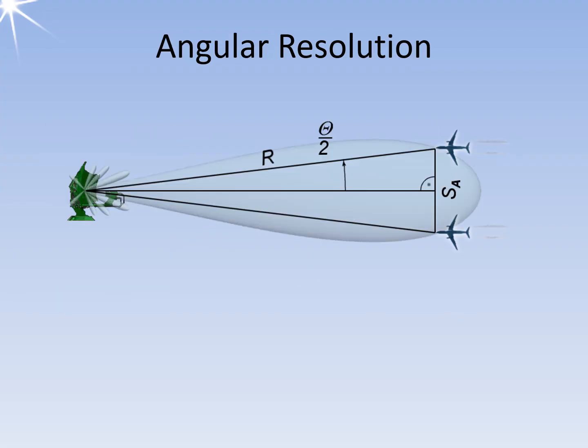Radar angular resolution is the minimum distance between two equally large targets at the same range which radar can distinguish and separate from each other. The angular resolution is a function of antenna parameters. It can be given directly as an angle or as a lateral distance between aircraft measured as a function of distance. The angular resolution characteristics of radar are determined by the antenna's half-power beamwidth, which is defined by the -3 decibel points. The half-power points of the antenna radiation pattern are normally specified as the limits of the antenna beamwidth for the purpose of defining angular resolution.